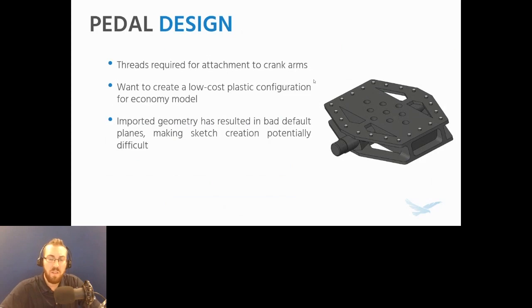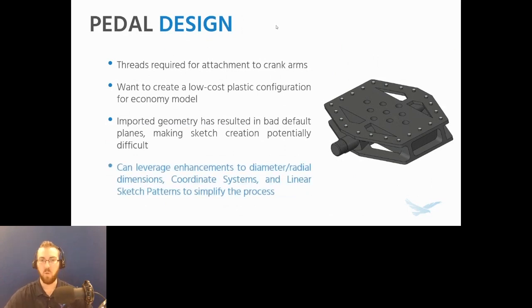Now, one thing that complicates this process for the pedal is that the pedal is an imported model. It was a STEP file. And some of you have probably seen this. Imported geometry often has a tendency to result in bad planes, and that can make sketch creation difficult. Now, you can take measurements and recreate planes and force this to work.